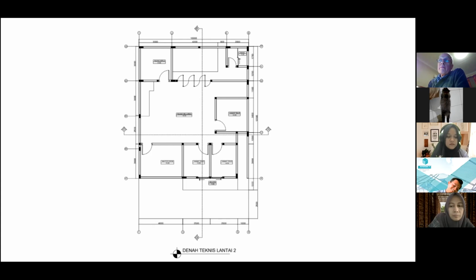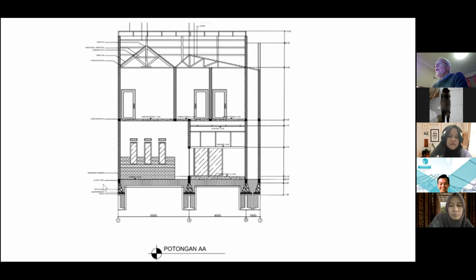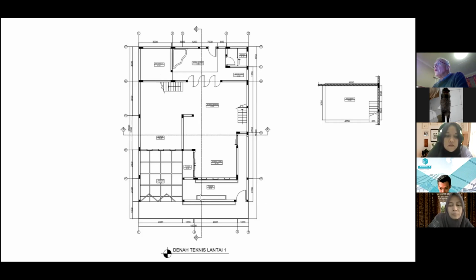So that's good news. Now we come to the x direction, for shaking across the building like this. We start with Lantai Satu, and we ask ourselves, have we got any seismic resistance in this direction on grid A? And the answer is no, we haven't, because of all these windows in this wall.